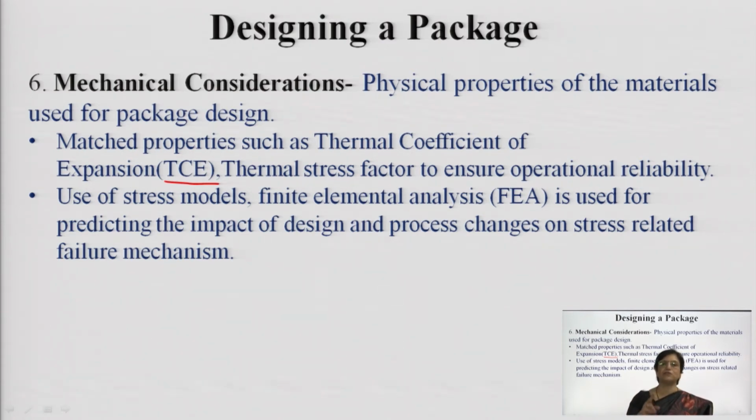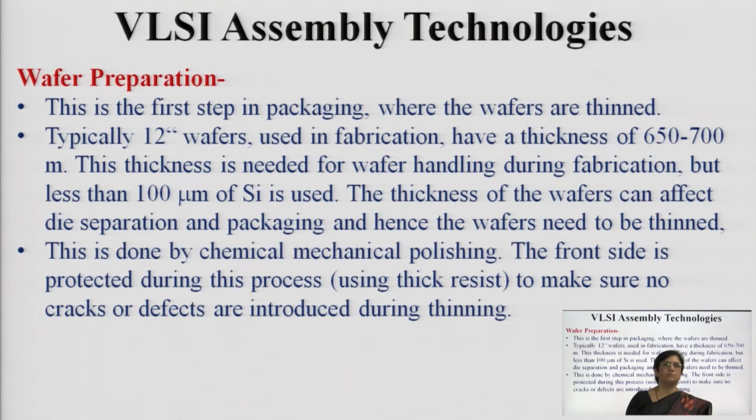So you have to have a matched thermal expansion coefficient, then you need to analyze the stress related issues, and these stress related issues are generally emulated or simulated using something known as finite element analysis, or FEA. This is a tool which allows you to simulate them, calculate them, estimate them, so that you can address all the process related and design related stresses, and countermeasures can be taken into consideration while designing against these stress related failure mechanisms.